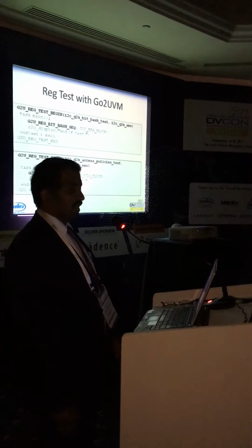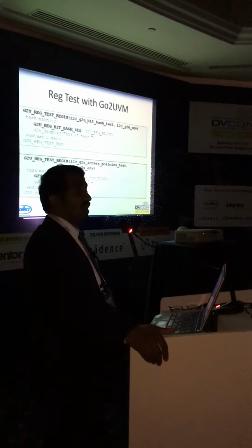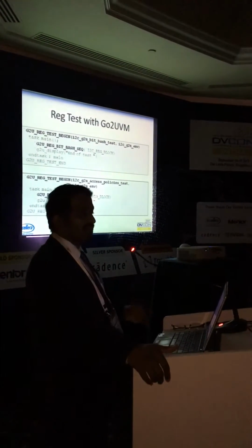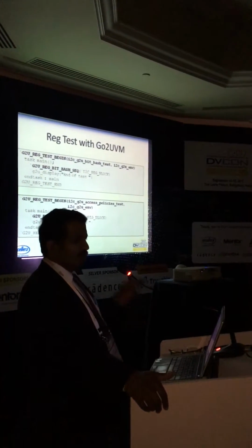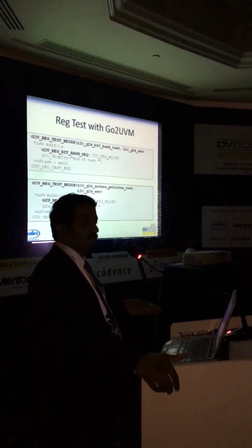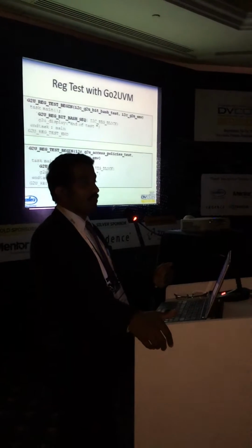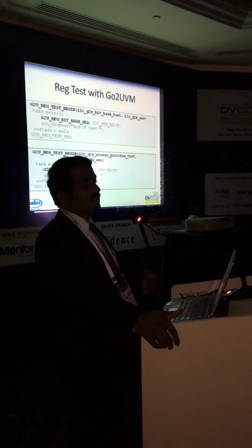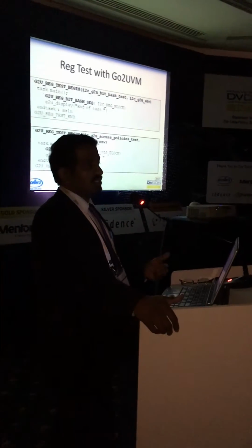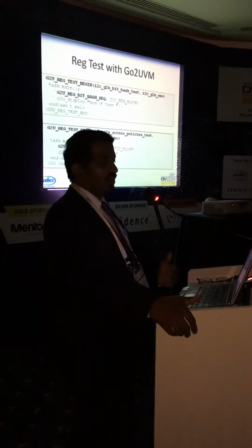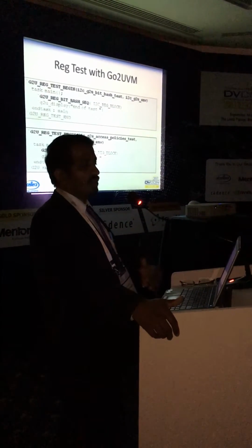If you want to do a reg access sequence, someone was asking, what if I have a read-only register? You do not have to write any more tests. Do this. Again, most of it is already in the UVM. The fact is, there is a reg access sequence and a bit bash sequence within the UVM layer. But unfortunately, not everyone is familiar with it, especially not the RTL engineers. And with this, the 50 registers in your design can be tested in a day or 2.